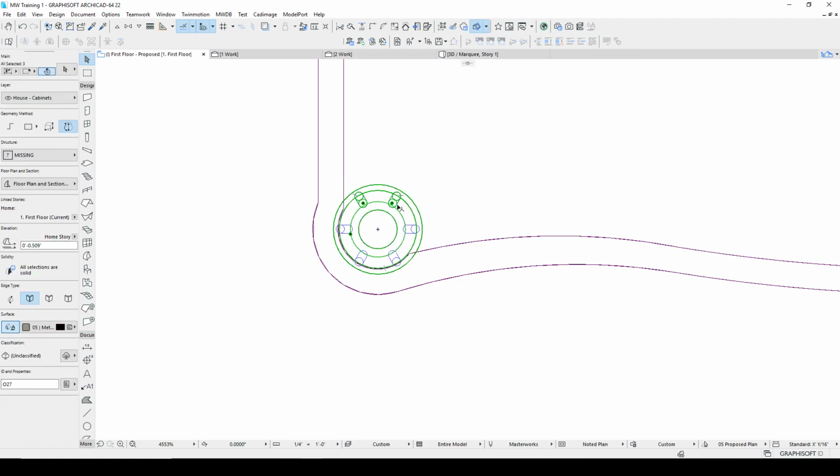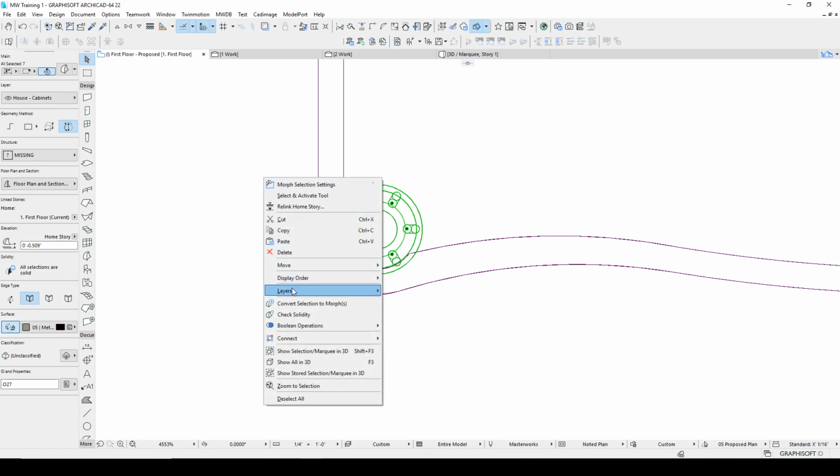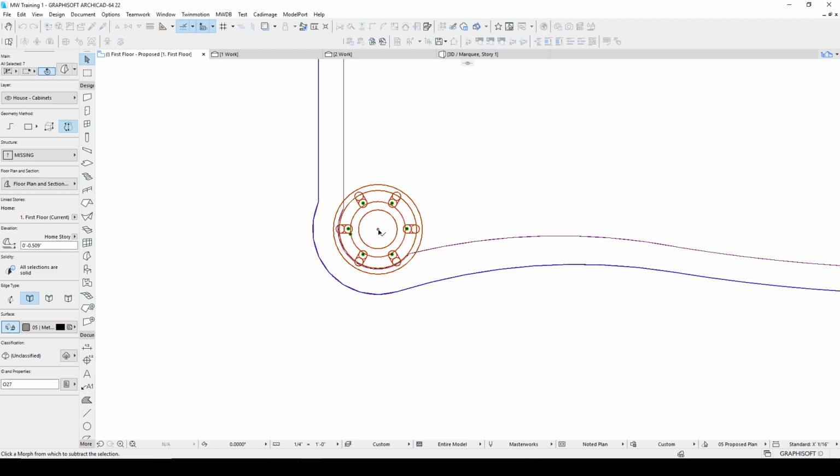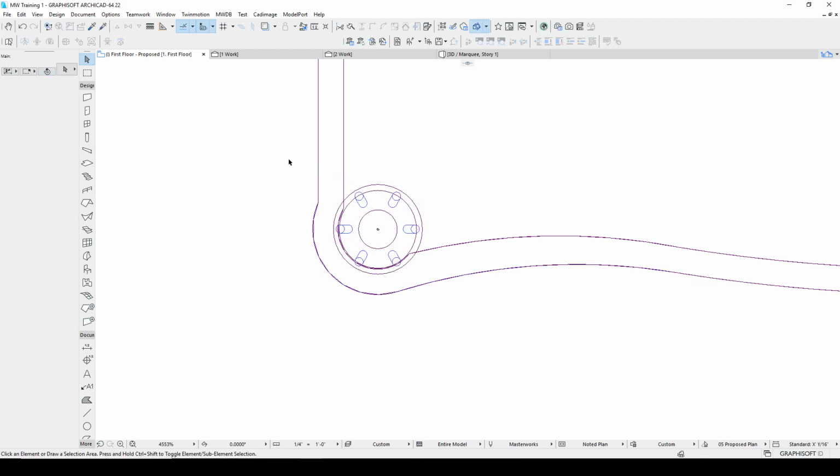And we can just do the Boolean right here. So choose all of those. Right mouse, Boolean, subtract, and then okay, so make on the selection, this is important. Always make sure you have this third option, which makes the selection direction sensitive.